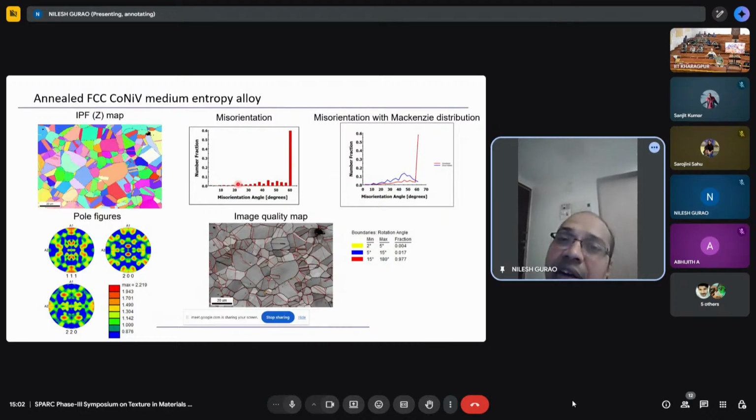That is in the numerator. In the denominator, what do you have? Summation of all the 4 grains that you have. The area of one grain is a square by 4, so a square by 4 plus a square by 4, 4 times. That is nothing but a square by 4 into 4, you get a square, right? So you had a cube by 2 in the numerator divided by a square. What are you left with, my dear friends? a by 2. So in this case, my number average and area average grain size is a by 2. Did everyone get this or not?